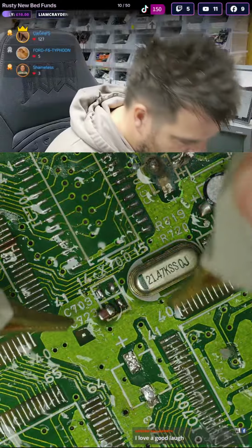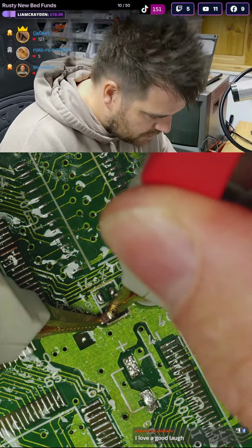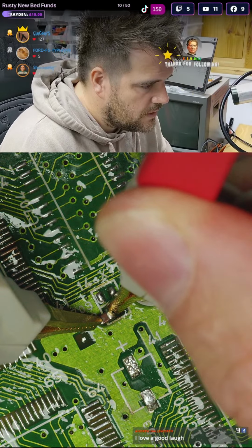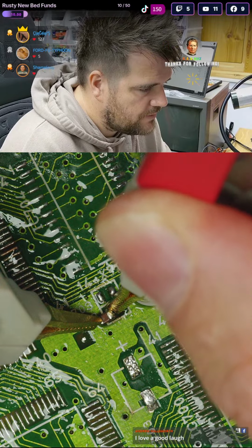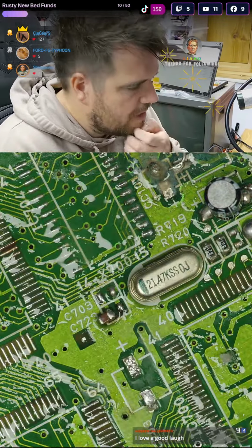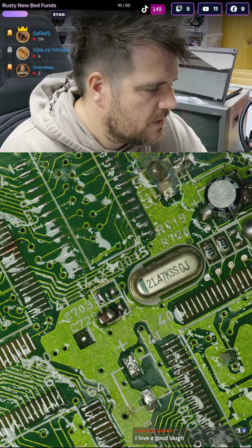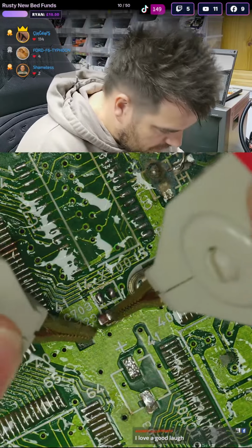Right, so this one we can measure. Now this one's 150 picofarad. This one's measuring. So we'll set the frequency to 100 Hz. We'll do a measurement in a few ranges.